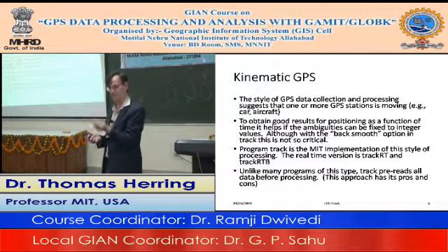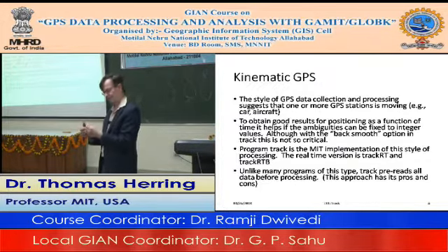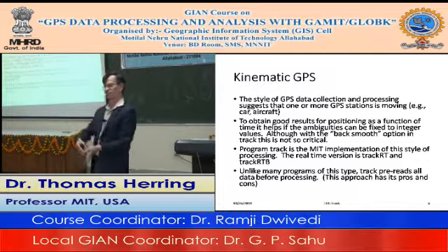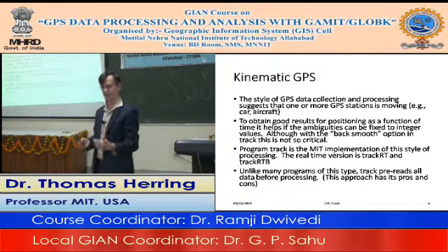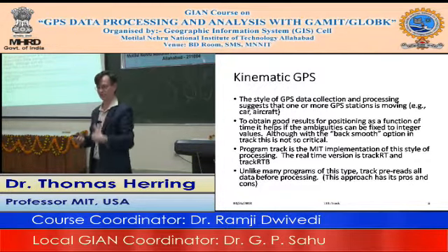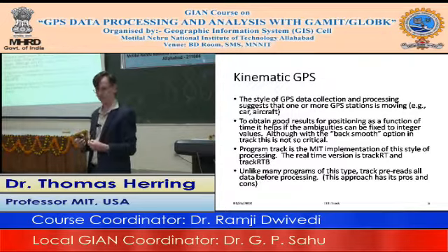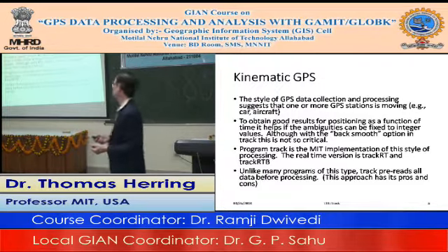So it's meant to be static. So the characteristic there is the Kalman filter, as it evolves with time, does not actually change the position of the station. It's always looking at the difference from where it is. And normally that's because when you're static, you're no more than 10 or 15 millimeters away. And then if you have a big earthquake come through, you might get 20 centimeters away or 30 centimeters away during the seismic waves, but you're very, very close. So it's not designed to let you pick up the receiver and move it 10 kilometers down the road. That's going to fail with this real-time system.